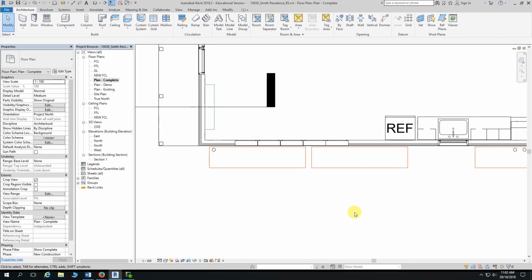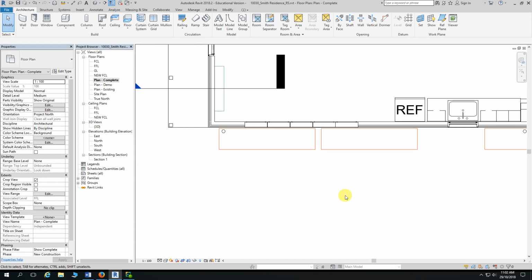It's just the fact that whatever we create in the project, we can't use anywhere else. I guess if you want to model up something very quickly, then the in-place editor is probably the best option. I wouldn't recommend that you do too much of it because of its limitations.